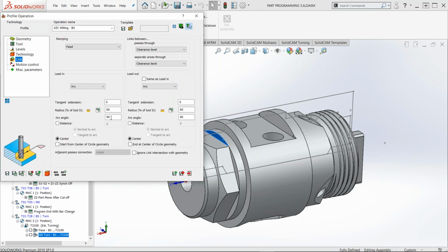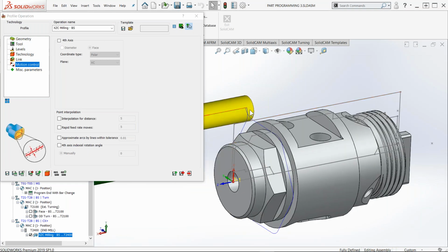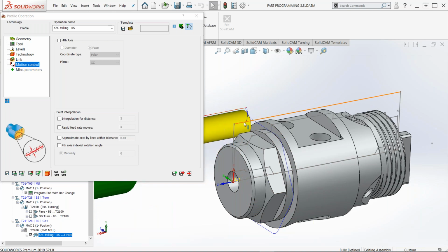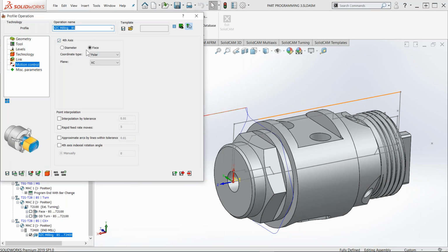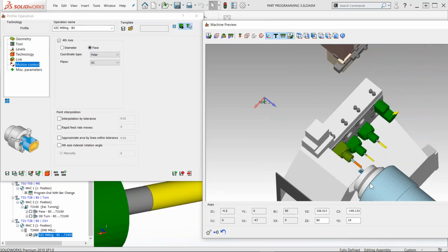Links, I'll just perform with a distance here, maybe 60 degrees. Save and calculate. All right, so we approach here. We'll do all the way around, but I would just like to do it with my fourth axis, from the face, polar, using the cycle of 12.1 on this machine. Nothing else more to check. The SolidCAM will automatically interpolate the C-axis, and all will be good.